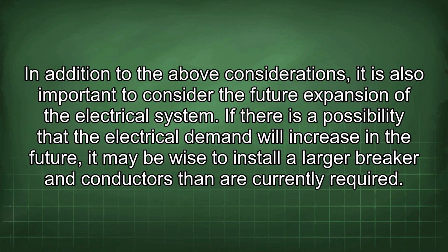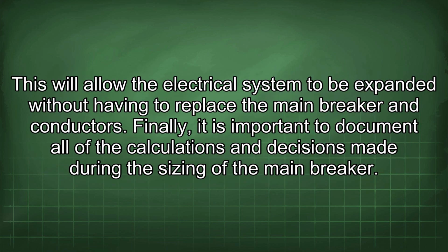In addition to the above considerations, it is also important to consider the future expansion of the electrical system. If there is a possibility that the electrical demand will increase in the future, it may be wise to install a larger breaker and conductors than are currently required. This will allow the electrical system to be expanded without having to replace the main breaker and conductors.